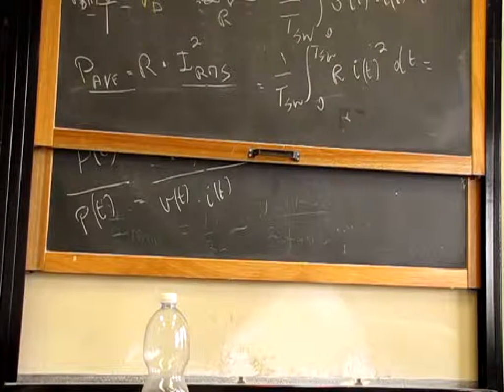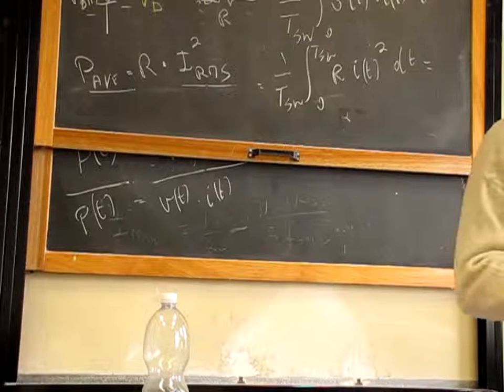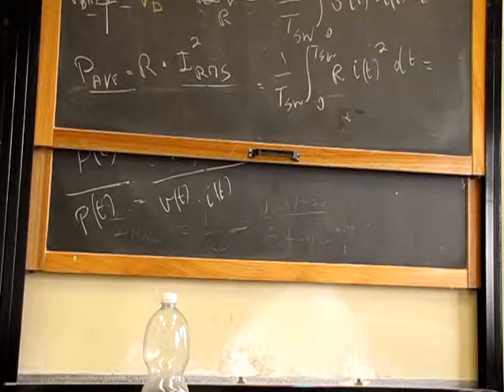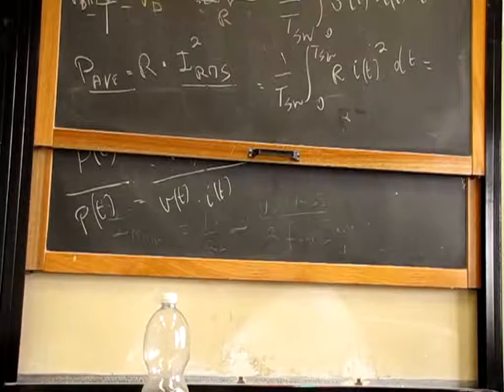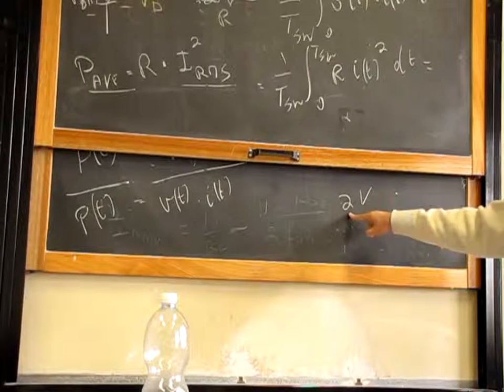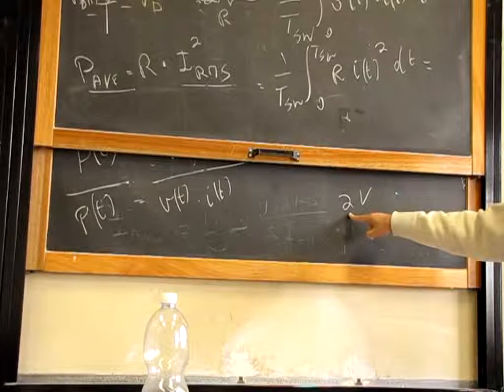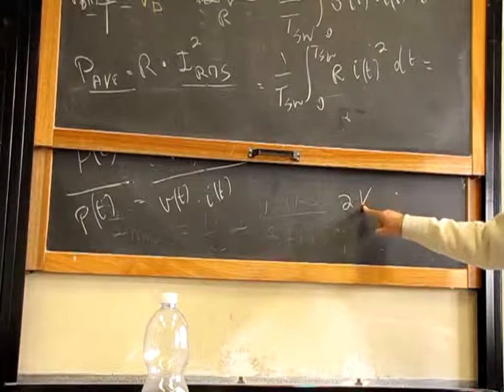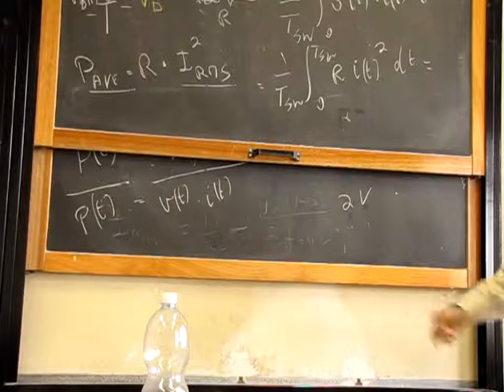In many cases, you hear, oh, 100 watts RMS. That is wrong for two reasons. First, RMS power is meaningless. What is important is the average power, or the peak power, let's say average power. Second, RMS watts don't exist. There are watts, not watt peak, watt RMS, and so on, like voltage. You can have 2 volts, and this voltage can be a peak voltage, could be an average voltage, could be an RMS voltage, but there is no 2 volts RMS, 2 volts average, 2 volts peak. Volts are volts, period.